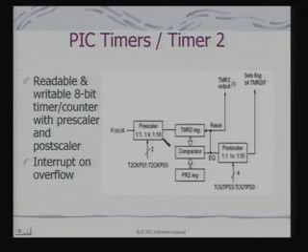That means this will divide the input when it is being fed to the timer. And a postscaler means what? The postscaler can also be set to different values for post scaling the output of timer 2. And these bits that we are showing here are control bits which can be set to select the different values for the prescaler as well as the postscaler.